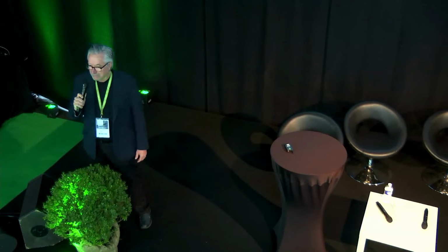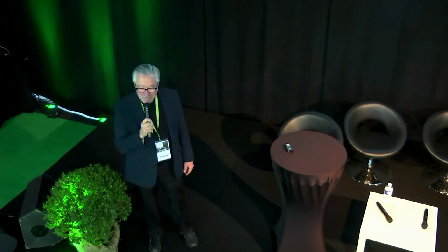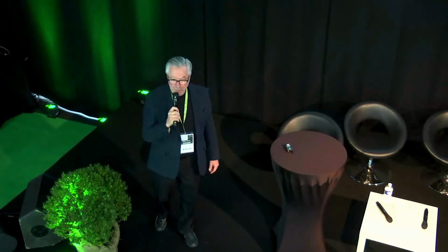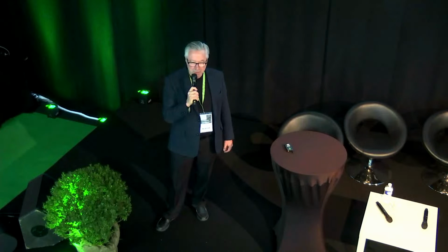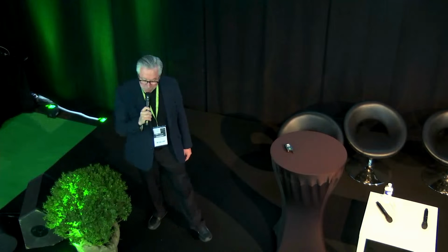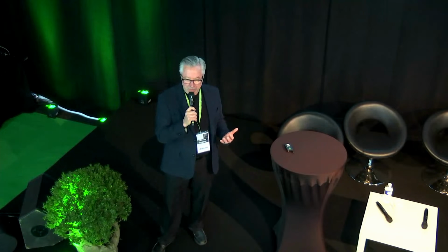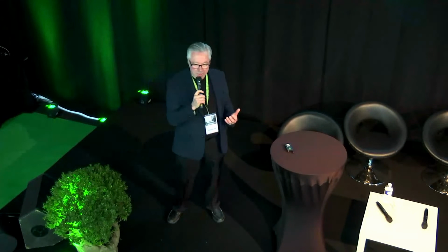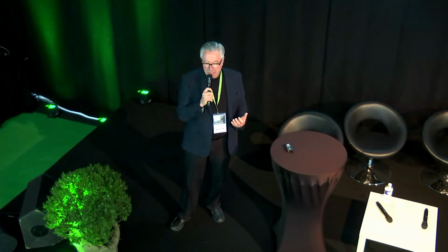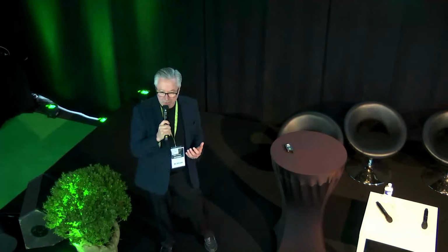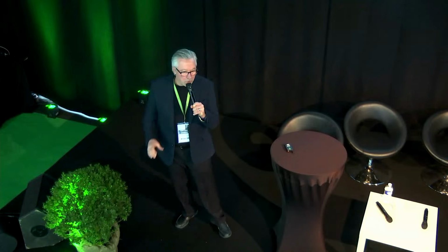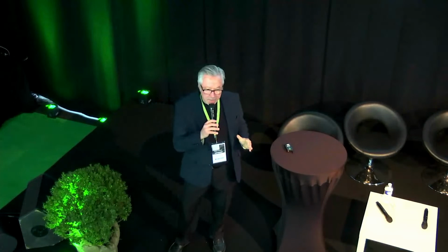Hello. I saw you at fiber. How much do you use in your product, or how much do you intend to use? In terms of fiber, I can't give you a percentage, but it's a fairly low amount. But what's interesting about the fiber, that's a great question, is that it's different than what you can do with concrete. With concrete, you can put about 3% fiber mix in, and with our product, we can get up to in excess of 10%. So there's an opportunity to mix different types of fibers in at a much higher level. We haven't begun testing of this yet, but our goal overall would be to use certain types of fibers in enough quantity that we could actually eliminate the use of steel rebar in certain applications. Thank you.